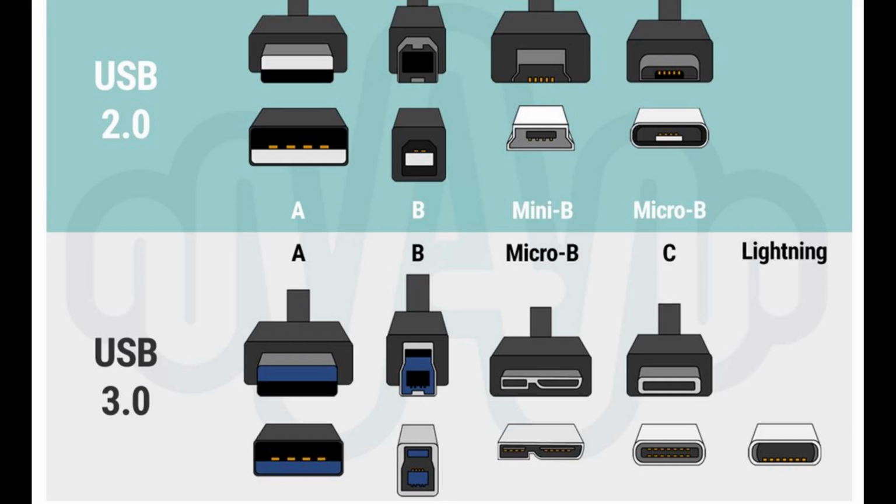USB has a strict tree network topology and master/slave protocol for addressing peripheral devices. Slave devices cannot interact with one another except via the host, and two hosts cannot communicate over their USB ports directly. Some extension to this limitation is possible through USB On-The-Go, dual-role devices, and protocol bridges. A host cannot broadcast signals to all peripherals at once; each must be addressed individually.